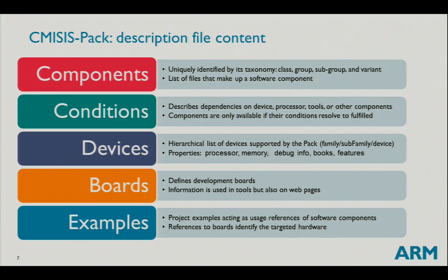At each level, you can specify the device properties: the processor, which memory is there, how the debug support is done, and other features, including documentation. It is done hierarchically, so you can save a lot of space, because you don't need to define the same information many times for thousands of devices. Similar is for the boards, and you can optionally have examples in a pack, dedicated either to a particular component or a particular board.